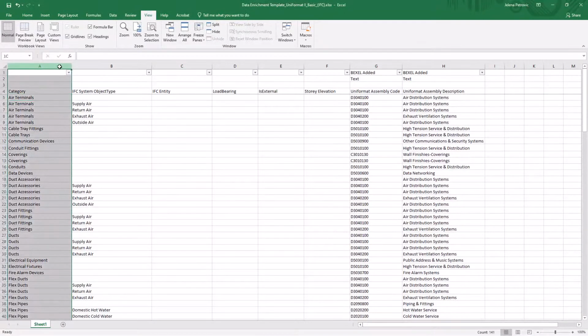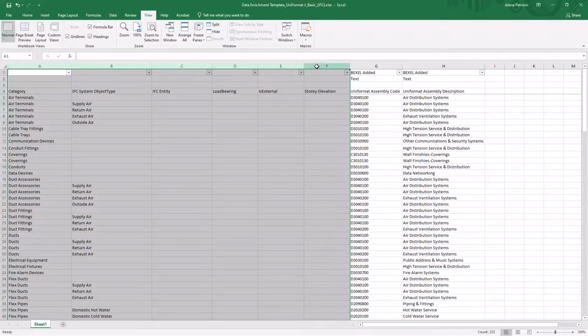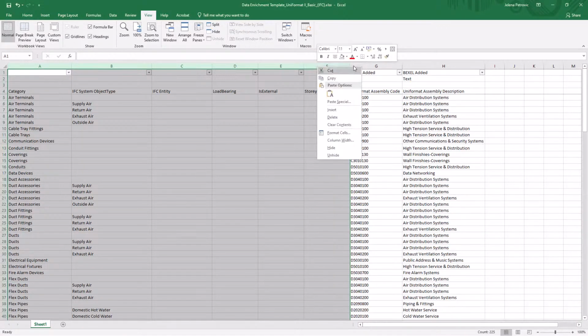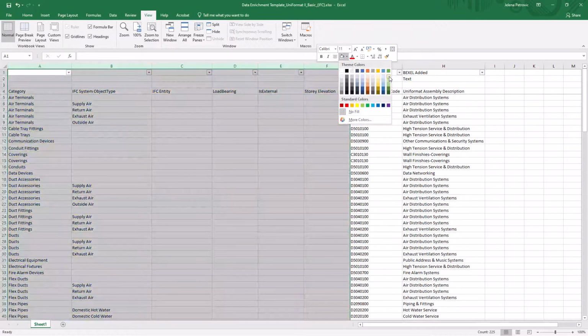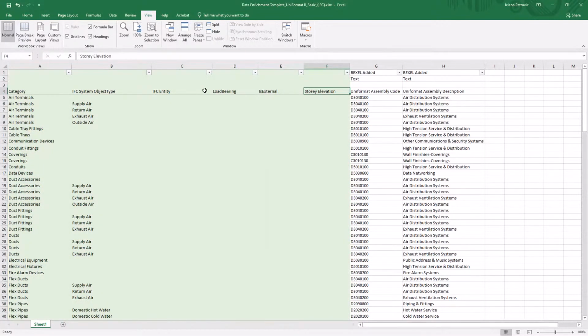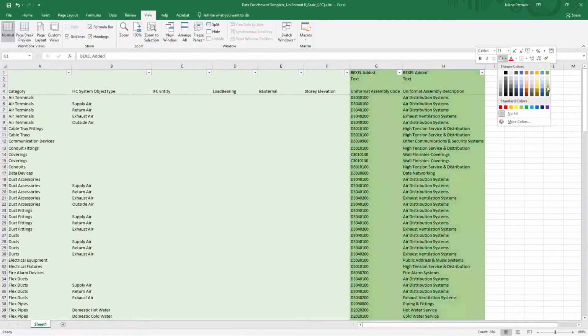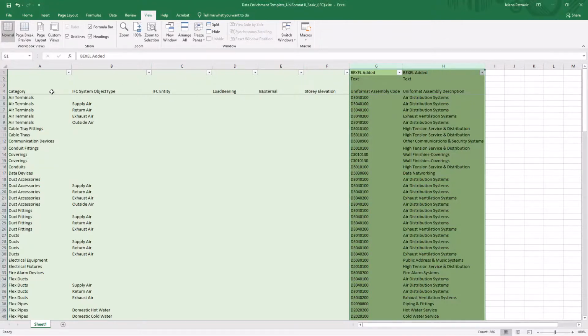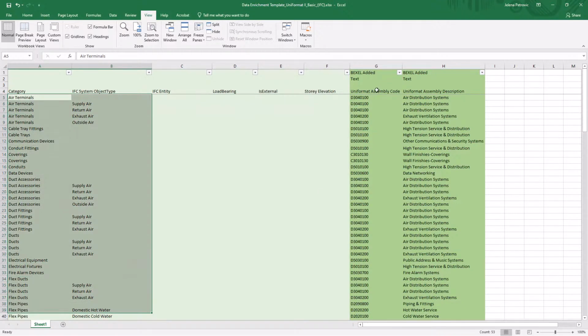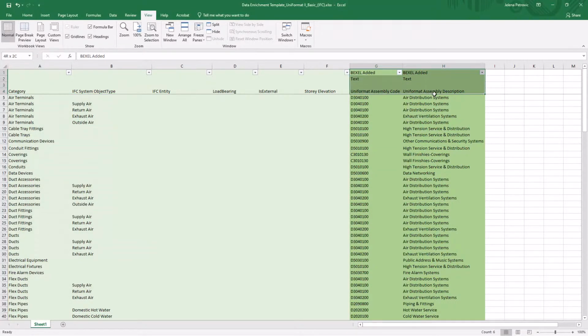Existing template contains two main sections. First one includes properties that are already defined within BIM model and that are utilized for filtering specific elements to which new properties will be added. Second includes properties we want BIM model elements enriched with. First section includes existing property names and existing property values, and the second, on the right side here, includes property definitions which will be added or updated, and values of properties which will be added or updated.